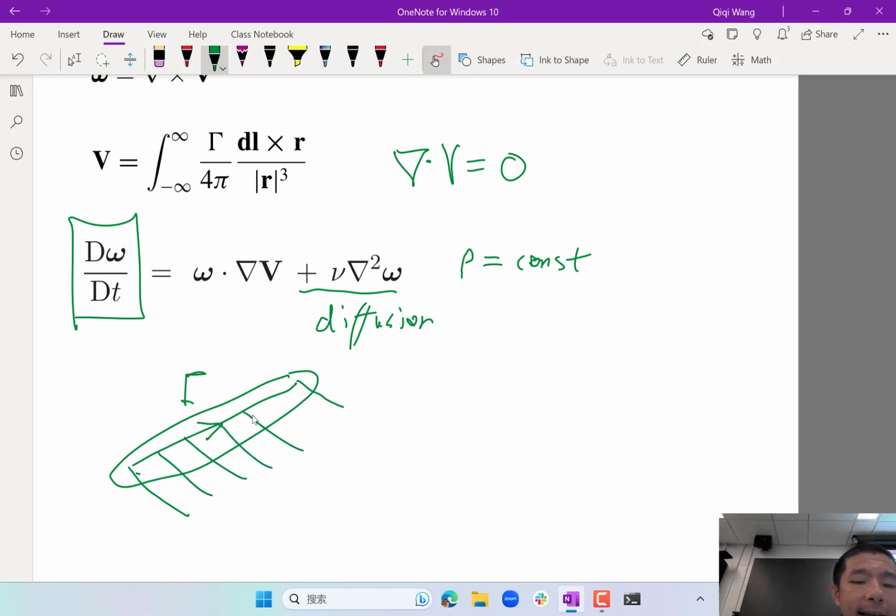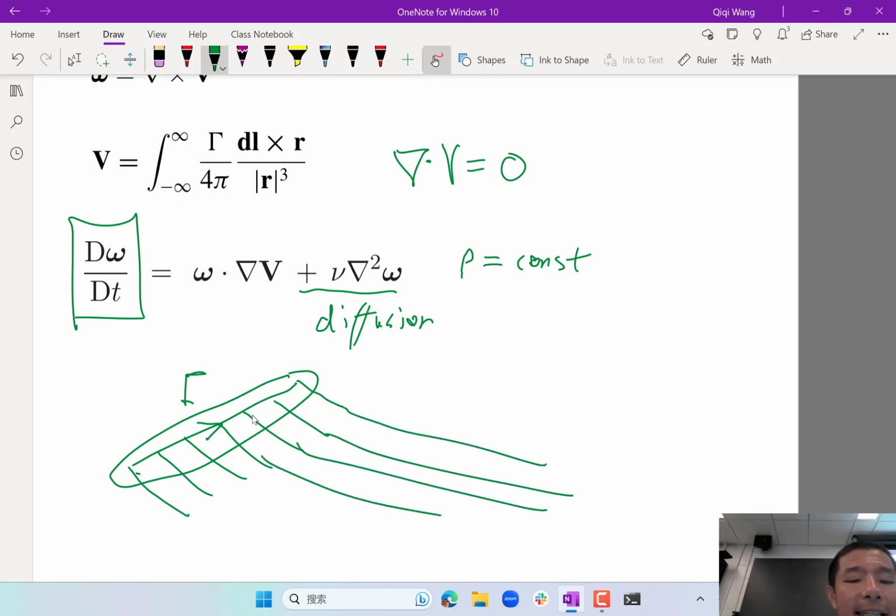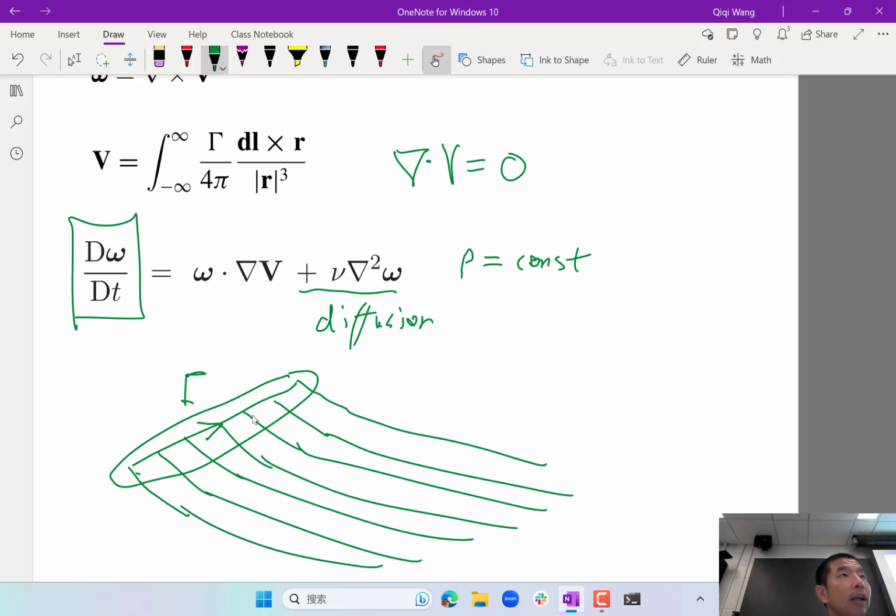Imagine this as an imaginary sheet. This goes down initially, and the downward motion would become less as you move further and further away from the bound vortex inside of the wing. So this is going to curve like that. Which means that if I have only a concentrated tip vortex that comes out of the tips, that tip vortex is going to go down and then go straight. So that's the first consequence that's different from the simple approximation we learned in unified.